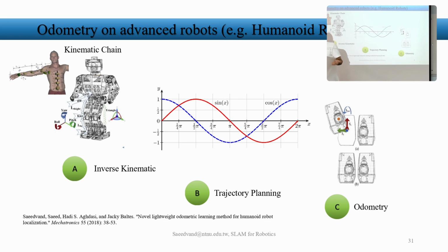So you need to generate trajectories on the swing, then lots of additional parameters on the Z, and maybe you need to combine 10 of these per arm, per each one of the joints, then you achieve a steady walk engine. But the whole concept comes from here.